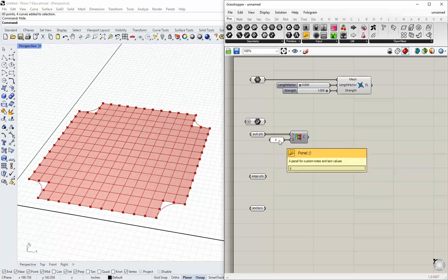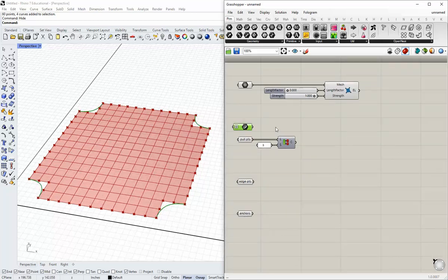This is going to repeat until the list is completely satisfied, right? So this number 3 here can actually be input as a pattern if you like. So it could be 3, 4, 2, whatever. In this case, we just wanted to repeat 3s until it finishes pocketing all the data points into sets of 3. And because it's divisible by 3, we have 4 lists. And we also have 4 curves. Okay, so these things we can now associate with one another.